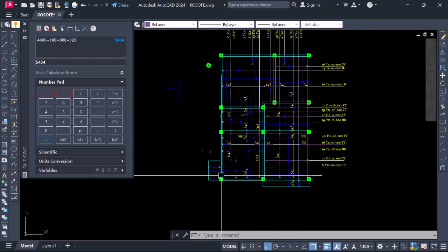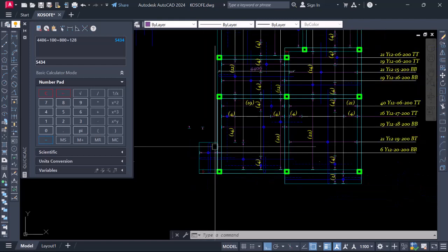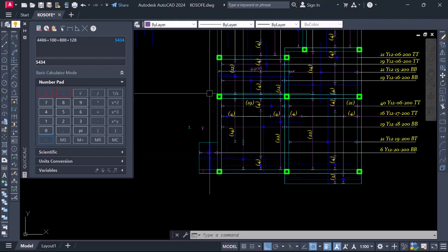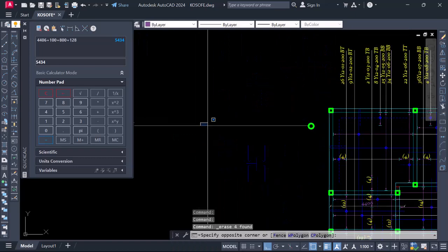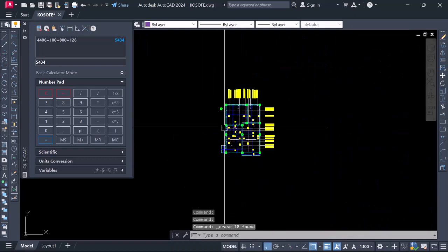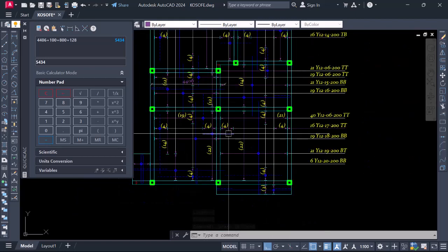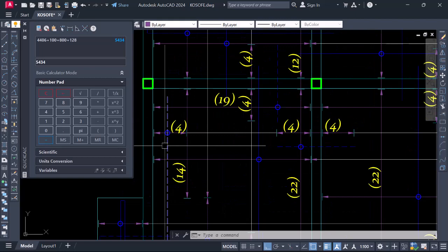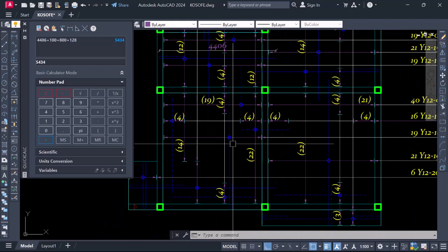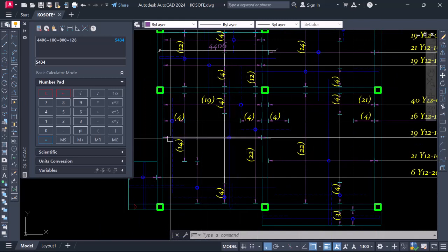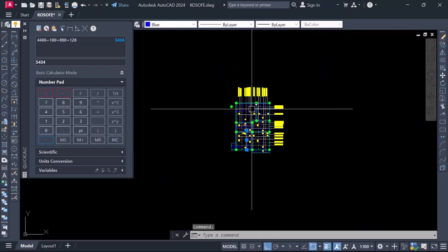All right. So in this direction, we have double reinforcement here because of the shorter span, right? Because of the shorter distance, and this is our cantilever. We are receiving the landing. Since we are done, let's take this off, because these are part of the design procedure. So take them off. So this is ready. If you look, this is running at the top area, so it's going to be on top of this. This will be running underneath, as we have the one at the shorter span under it and the one at the longer span on top. So that's what we just did. A typical example of this is this.